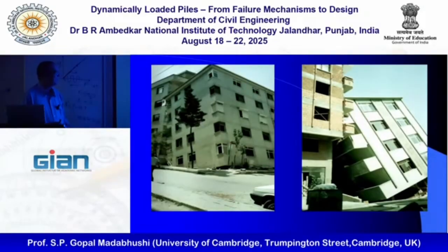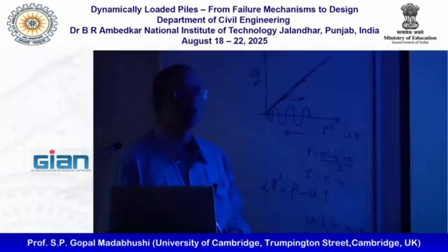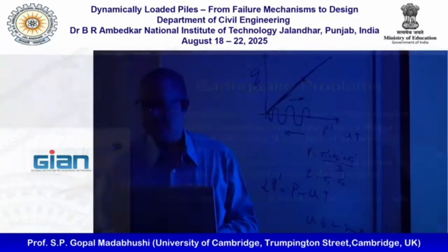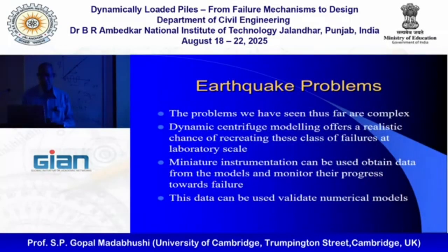So clearly, these are quite complex problems where we're talking about interaction between the soil and the structure, and also how the soil behavior changes under cyclic loading. Now, dynamic centrifuge modeling offers a realistic chance of recreating these failures at laboratory scale.